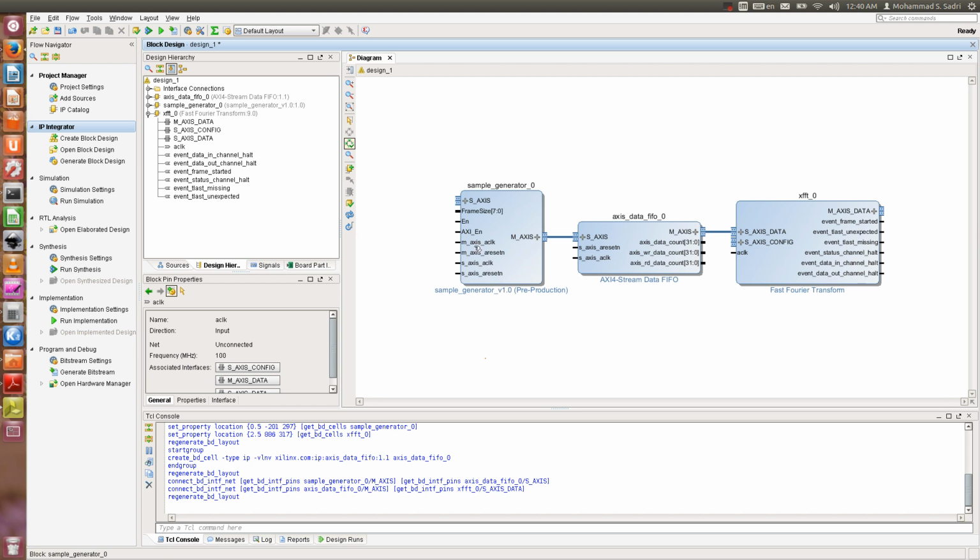And for this design we are supposed to have 2 different clock domains. I will talk about this just a few minutes later. We have the FFT module. There are lots of points that I should say about these 2 guys. I will tell them, but for now let's make the chain complete. So after the FFT module, I want to somehow store the results of the FFT, the results of the processing that I have done, on the DRAM memory of the Xilinx ZYNQ device.